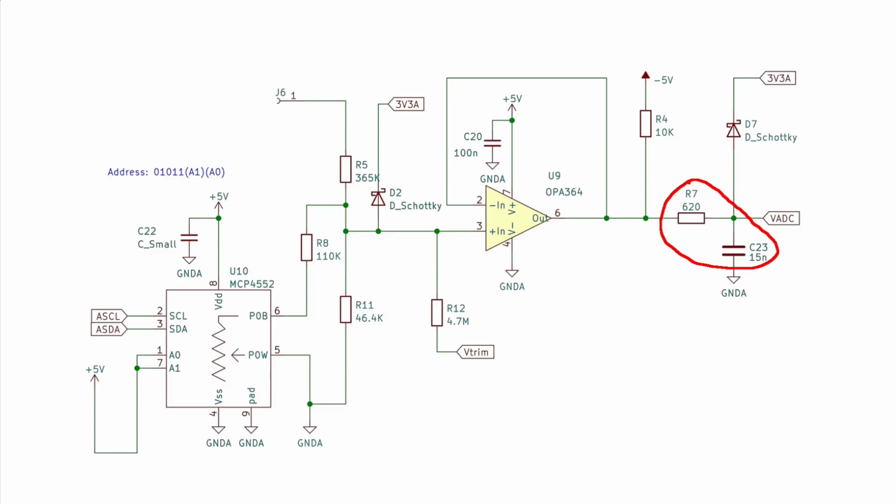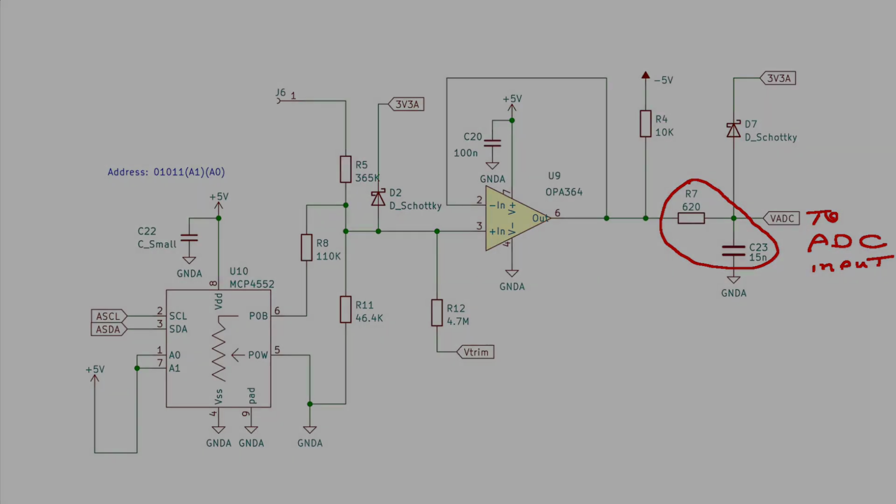Turns out anything over about 15 nanofarad in a type C0G 603 package is very hard to come by. So I increased R7 here a bit and went with the 15 nanofarad. It's feeding a 5 picofarad sample and hold capacitor, so I think it will be fine.